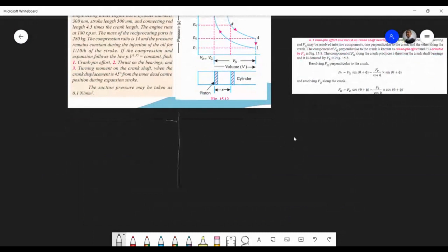This is probably the most difficult example you can get. That angle there is something like 45 degrees. Stop dead center, got your piston over there. Expansion, that's FL, moving down. Therefore FI is going this way, FL is going that way, and your weight is going that way.